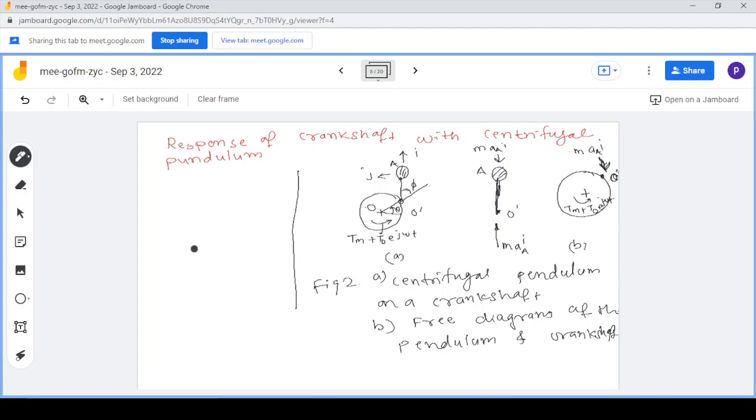So what is the condition we have studied here? We know the conditions for self-tuning. I am rewriting the conditions of self-tuning again. R by L is equal to N square for 2-stroke, and R by L is equal to N by 2 square for a 4-stroke.